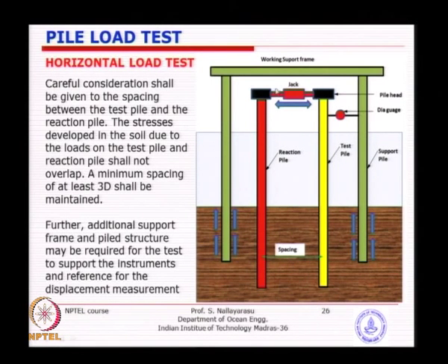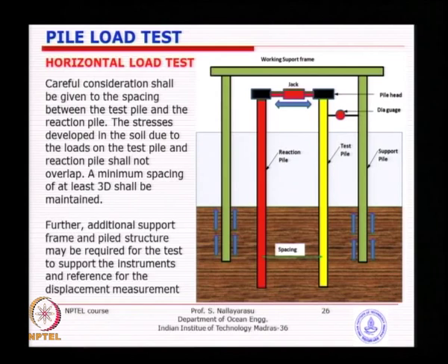Once you have wider spacing, mounting of jacks becomes a problem. You need to design a frame, and that is going to put you into a support system. Together it has to be mounted onto the 2 piles, which need to be free to move. So that is one of the challenges.